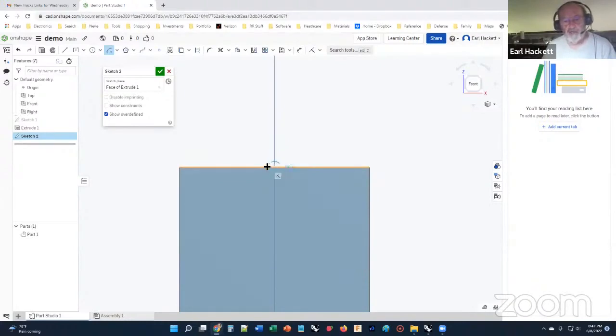And now we're going to create a center point arc. Now I notice I keep my cursor on the edge. I click 1, and I put it on the edge and click 2. We now have an arc. Radius of 2.1. Well, okay. I'm going to measure it. I'm going to set it to a radius of,